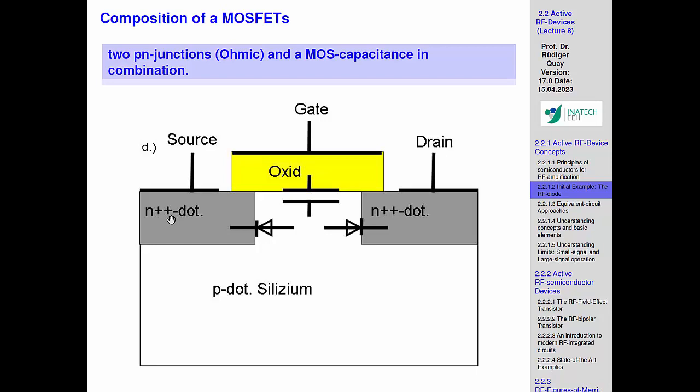Schottky. It's a Schottky diode, so it's not a good one, but typically it would be a Schottky diode. And then we were trying, again, this idea of tunneling, that we put so many carriers near the interface that this Schottky contact transforms by increasing the density of states at the interface, you would say physically, but it's very simple. You just put in so many carriers that they tunnel through this Schottky diode barrier, and then you effectively get a very low resistance ohmic contact.